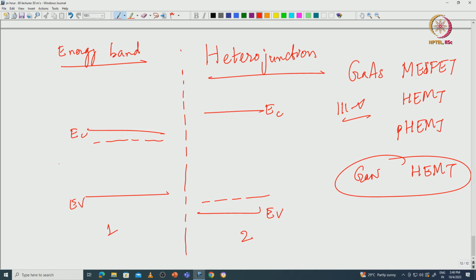And what you do is that, suppose I will take the black spot here, you fix this point where this conduction band is meeting, you fix this point where the valence band is meeting. Then I will choose a different color, maybe the blue color. You fix this point where this conduction band is meeting, and you fix this point where the valence band is meeting. Now the conduction and valence band from both sides are pinned to these black and blue dots, so they will not move.